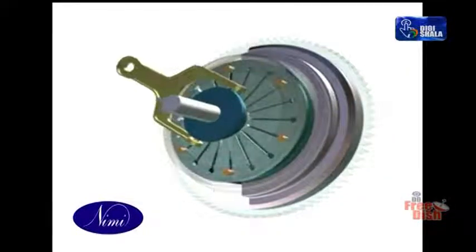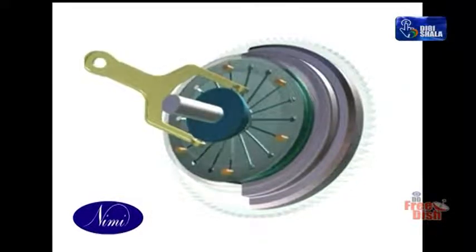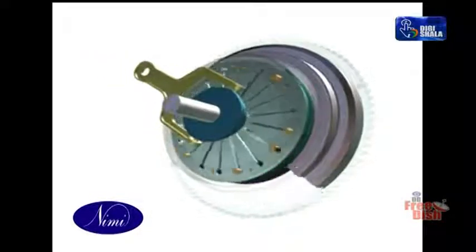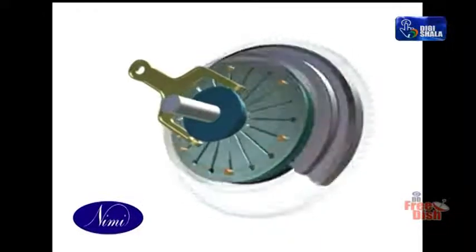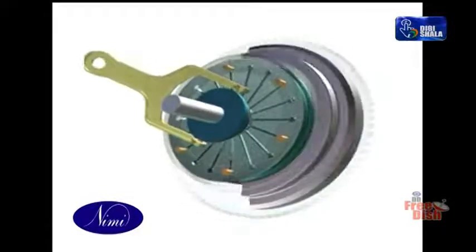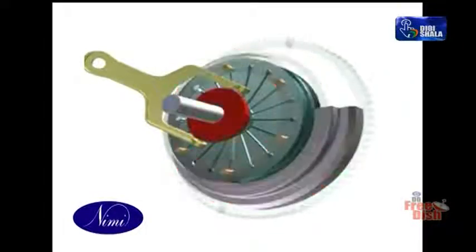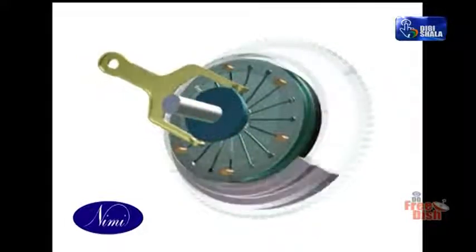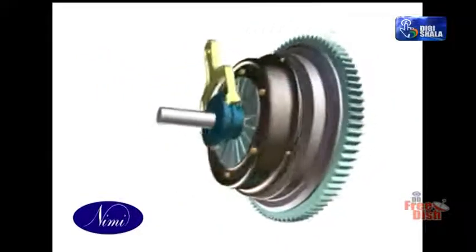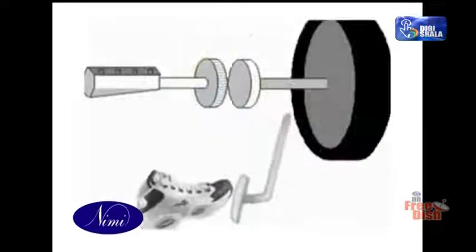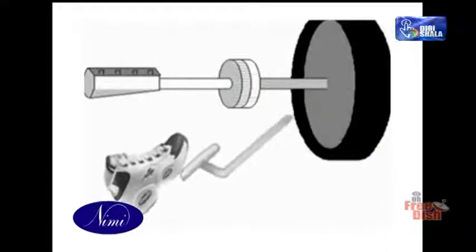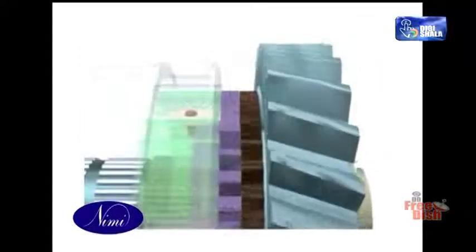Friction clutches. A friction plate sandwiched between the engine flywheel and a spring-loaded pressure plate transmits the drive to the gearbox. The extent of the drive is controlled by the force which is clamping the plate. Lowering the driver pedal causes disengagement by separating the friction surfaces. During this operation, the force of the spring is taken by the driver. Initial upward movement of the pedal causes the friction surfaces to contact. Further pedal movement allows the full spring force to act on the driven plate to ensure that all plates rotate at the same speed without any slip.